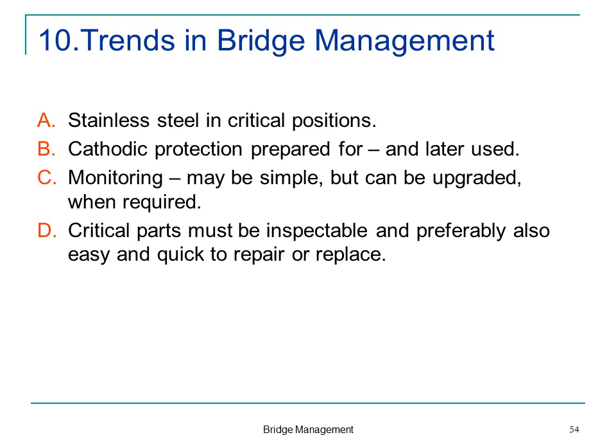We are now in the last point. That's really the trends. For instance, reinforced concrete bridges, I mean, we have built them for 150 years. They still have deterioration. And some of the things we can do is, we could, for instance, say, why not use stainless steel? When it is a problem that the reinforcement corrodes, then why don't we use stainless steel? It can't corrode. That would be a wonderful idea.